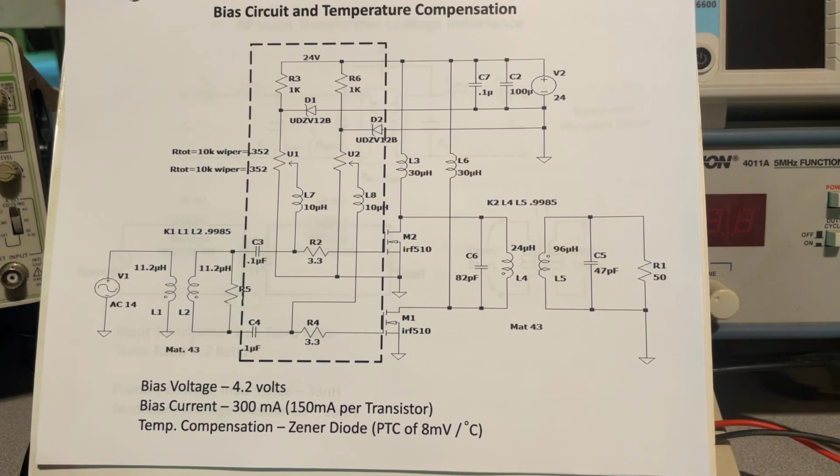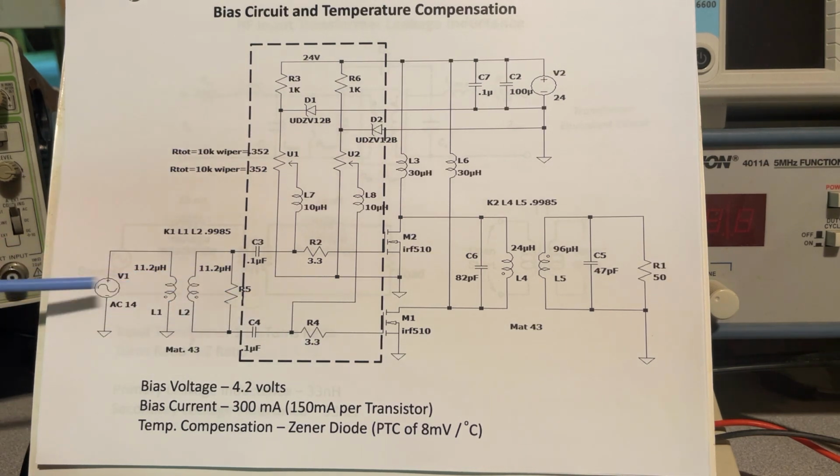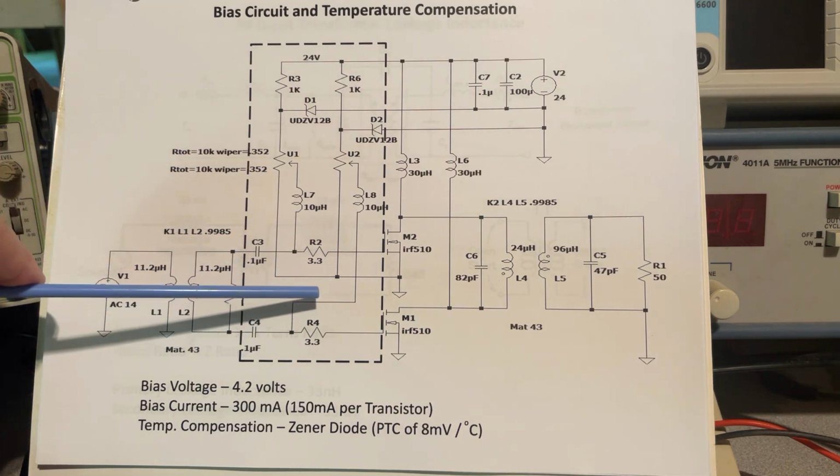RF Man here. Today I want to continue my discussion on how to design, build, and test an RF amplifier. In part 2, I showed how we could use LTSpice to measure the input impedance of a circuit, and I demonstrated that with a transformer using different turns ratios to match to 50 ohms. So those of you who viewed that video, we talked about the turns ratio and the impedance ratio and how that's used for transforming the input impedance to match the output impedance.